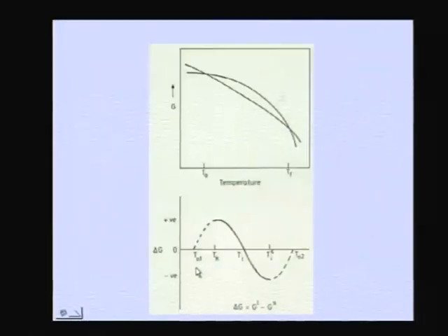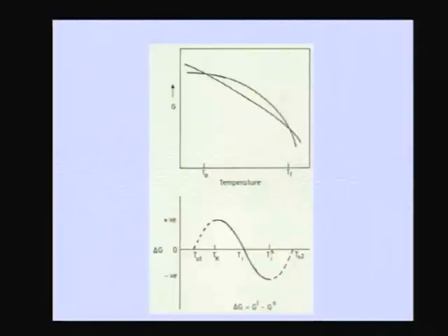So we cannot still talk about the free energy of the liquid below Tk. As a result, though thermodynamically one can calculate those free energies and talk about what is called a T0 temperature, that T0 has no meaning, because by the time you reach Tk, the liquid has already vanished, it has transformed to a glass. So there is no liquid left for it to transform into a crystal. As a result, we show this part dotted.